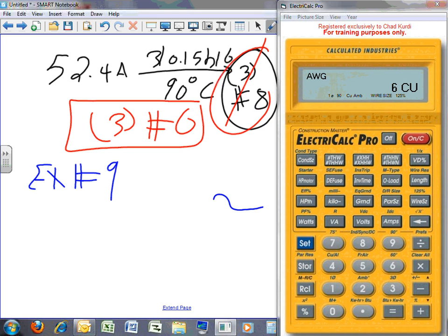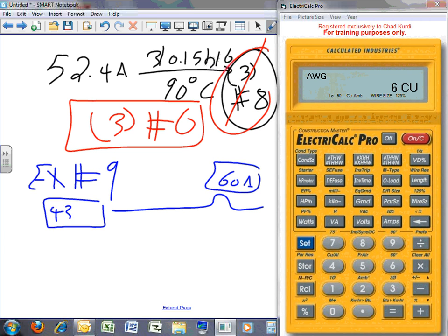The reason why I like to keep the same example, guys: 60-degree column and 43 amp, non-motor, and continuous. I will remind you that was number 6. Take this. I'm going to do two derating now. Number 1, let's go get you a few conditions here.